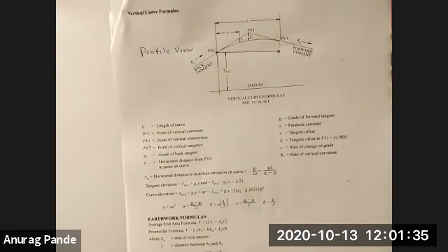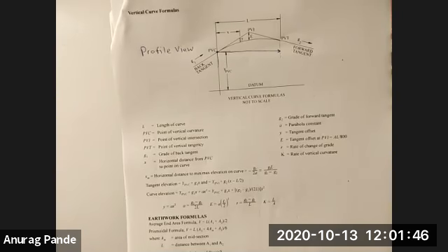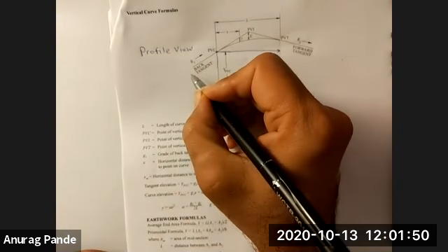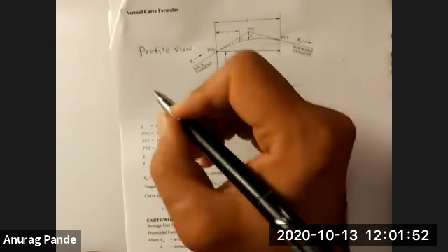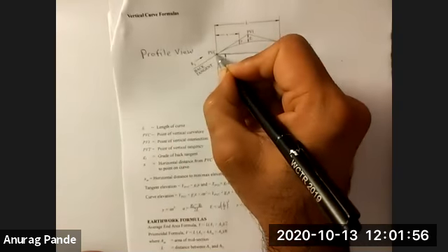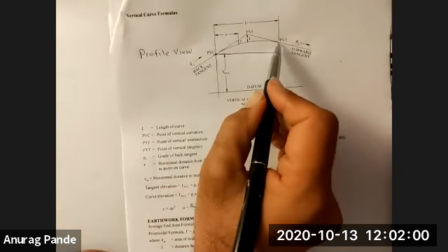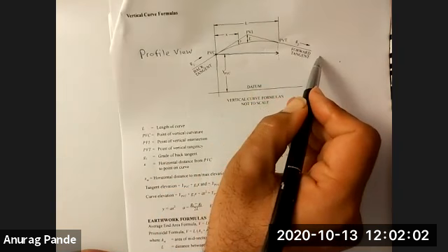The idea is still the same, but right now, why do we need vertical curves? We need vertical curves because we are trying to figure out how there should be a change in elevation. Okay? So now we are looking at the profile view and you're navigating on this chart, you're navigating an upgrade here. And then at the end of the curve, you're navigating a downgrade.